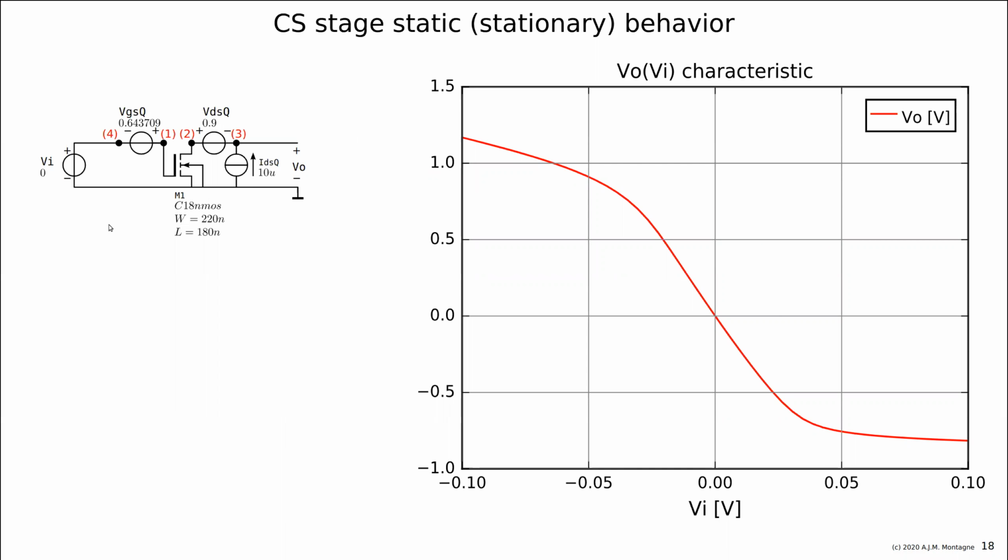So here you see the bias device again. And now I'm going to plot. I'm not going to plot all the characteristics. We are just going to do voltage to open circuit voltage and voltage to short circuit current. We could have done also the output characteristic. Well, maybe this is nice to do for yourself. You can build the circuit in the simulator, drive it with a current and measure the voltage across the current source. Then you have the output characteristic like IO, VO.